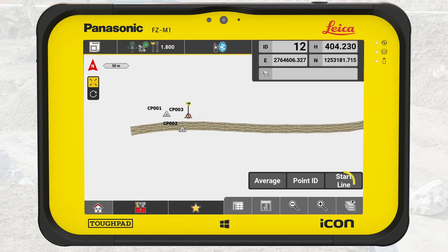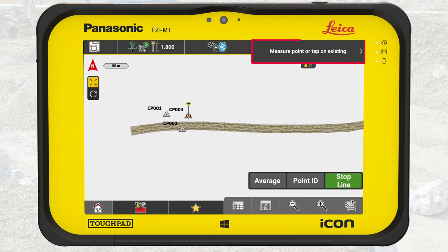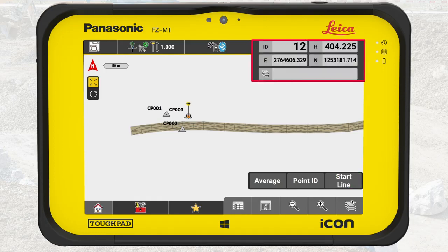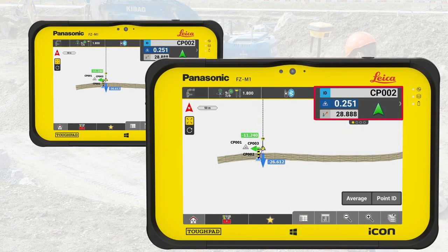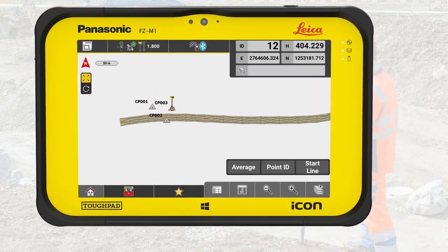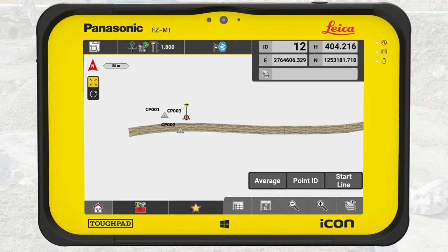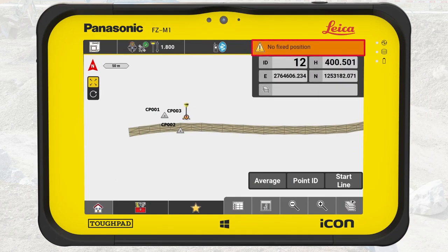It shows three forms of information: text guidance for the next steps while you carry out functions, values of the actual measurement, and guidance text and an arrow leading you while staking out an element. In case of an error, a warning bar appears above the information bar. You should take these warnings seriously and follow their guidance.